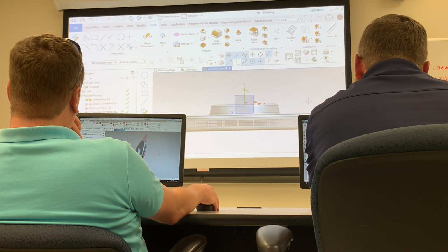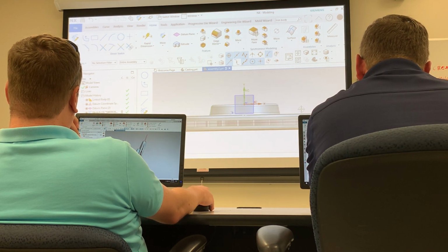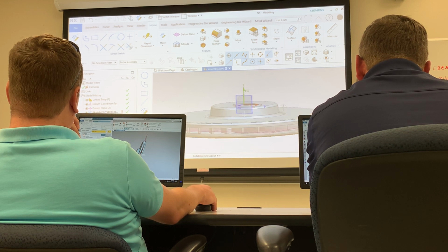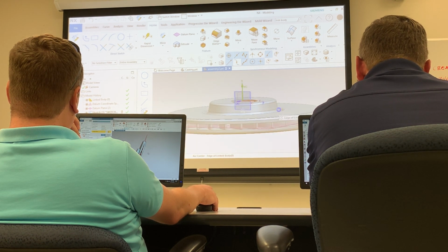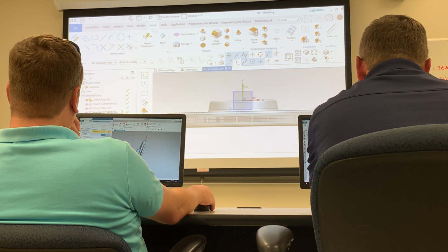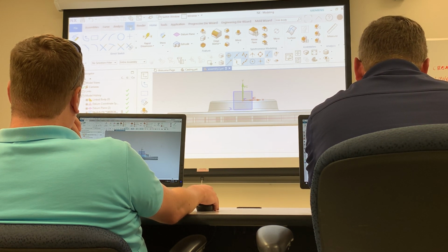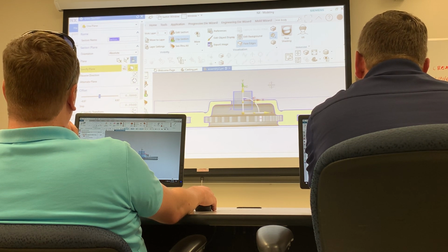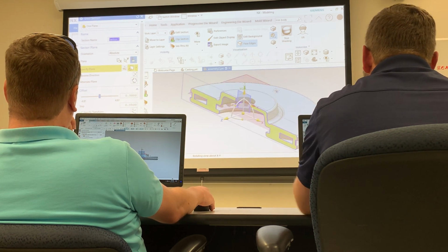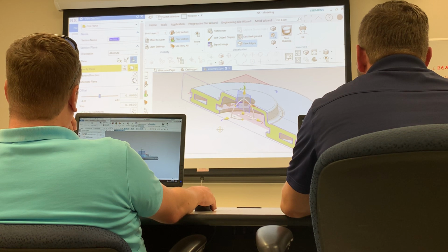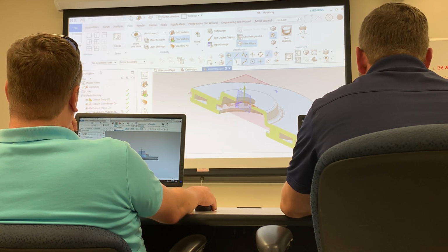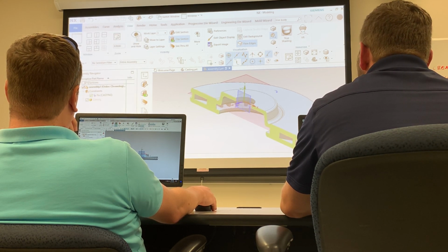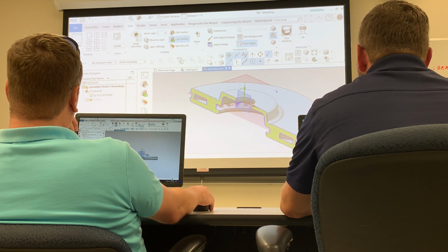Now it's kind of hard to see what's going on here, and it's going to be important that we don't gouge in here on this inside area, so we need to be able to see that information a little bit. So I'm going to go out to the view and put a section view on there. Now I got lucky that time, and he put the section view right down through the XY plane. Oh, you probably don't have this turned on. You can see the actual sketch. I mean the section lines.